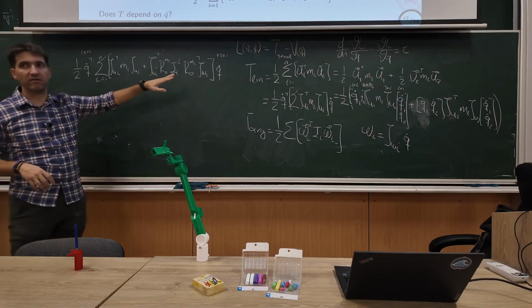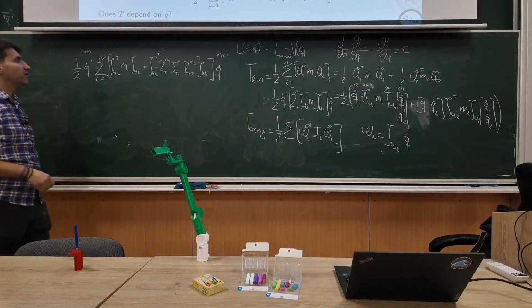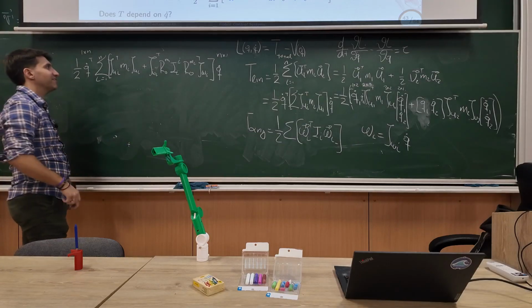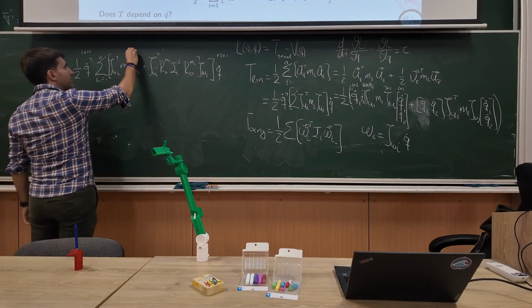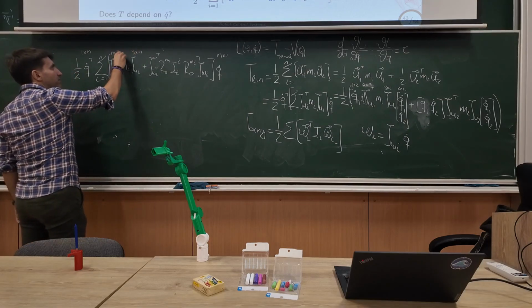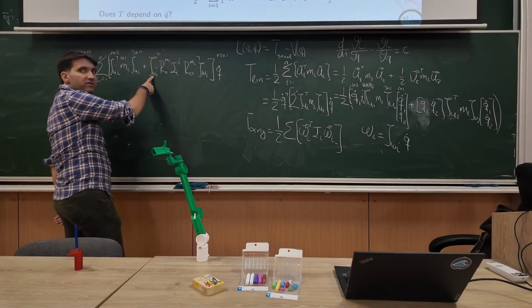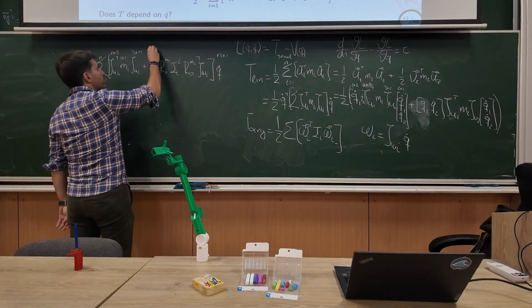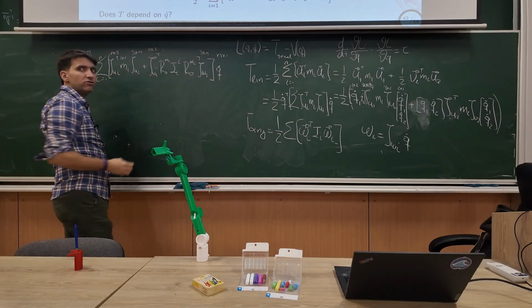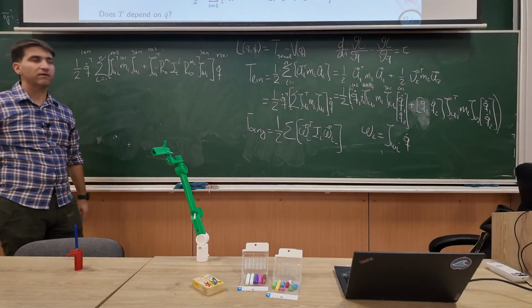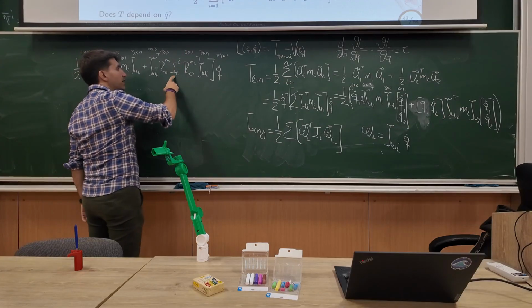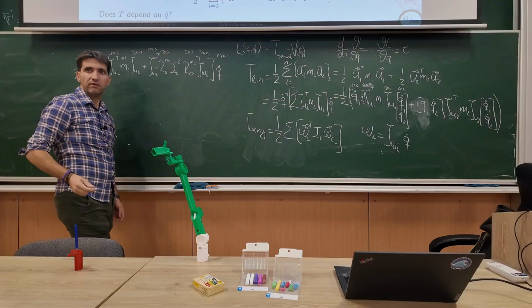So basically all these Jacobians have the same size. Almost? Oh, it's linear, 3. Right, so this will be 3 by n, and this will be n by 3. This is scalar in this case, right? The angular Jacobian, the same thing, right? n by 3, 3 by n. What are the orientation matrices? 3 by 3. And the transpose 3 by 3. And moments of inertia, 3 by 3.